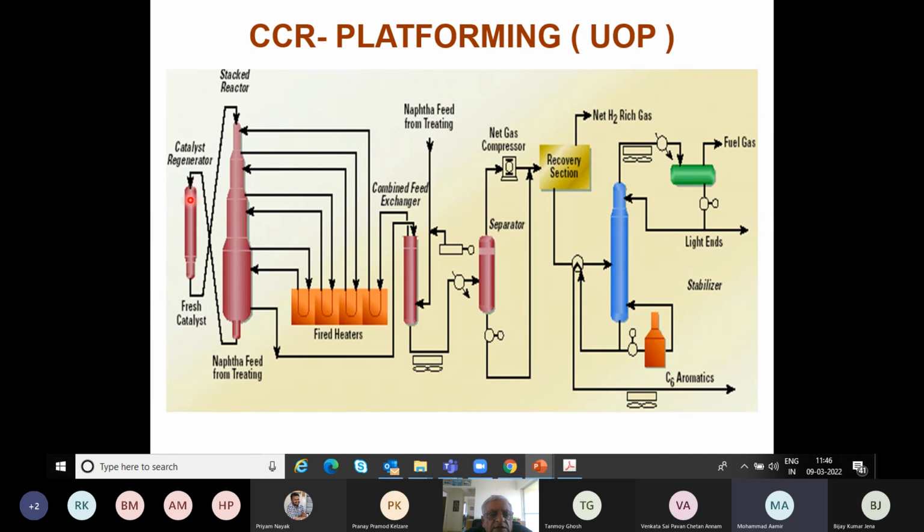And here actually the regeneration takes place. So this is the catalyst regenerator, where from the top to the bottom, you get fresh catalyst. What reaches the top is the spent catalyst. What comes out from the bottom is the fresh catalyst, and this is then lifted along with hydrogen. Now it's no longer nitrogen or air, but it is lifted with hydrogen because this is a hydrogen-rich atmosphere here. So this catalyst is lifted by hydrogen to the top and the journey continues.